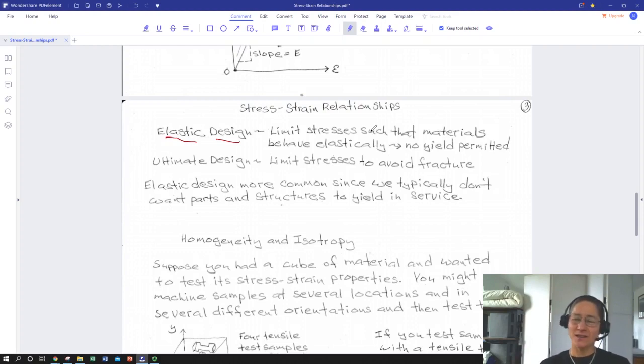Furthermore, customers and users of our designs do not always use them in the way we say. This is why what are known as live loads, that we can't control, what somebody puts in a building as opposed to the weight of the building itself, for instance, have higher safety factors. So we don't know what somebody's going to do. We're not there to tell them, "No, don't put that there, that's too heavy." So we use a bigger safety factor.